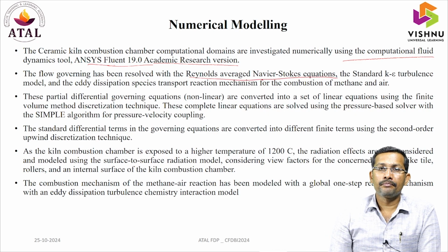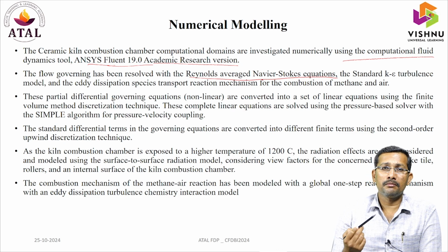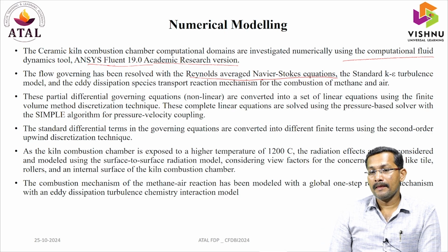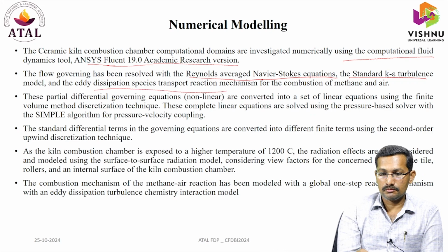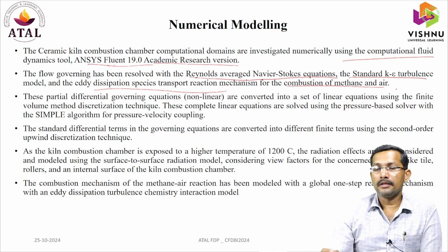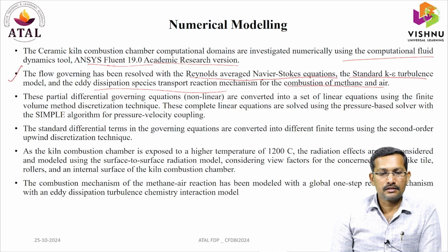In the beginning, I told you that fluid dynamics is controlled by the governing equations: the continuity equation, momentum equation and energy equation. Those equations we write in the form of Reynolds-averaged Navier-Stokes equations, called RANS equations. Those RANS equations, the standard k-epsilon turbulence model and the eddy dissipation species transport reaction mechanism are used for the combustion of methane-air. This is the complete setup of the governing equations we are considering.